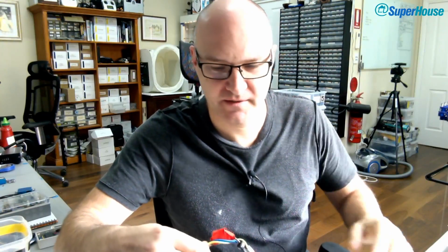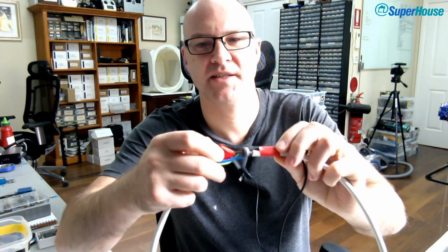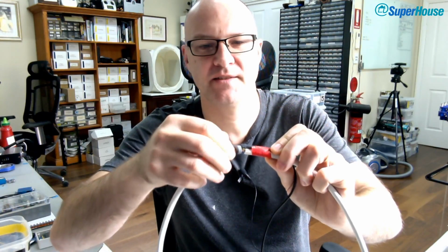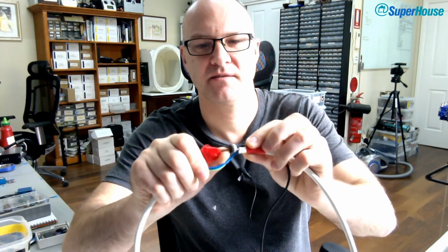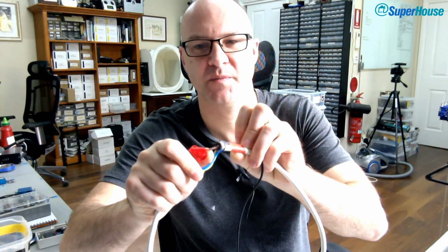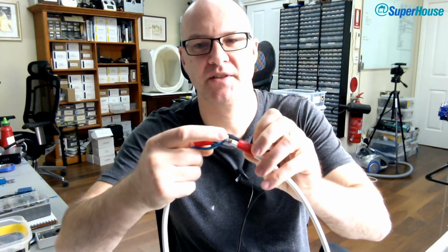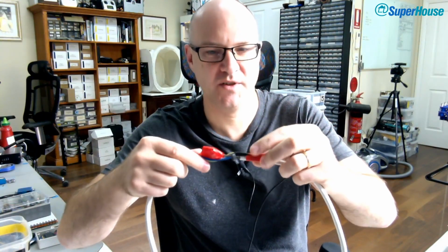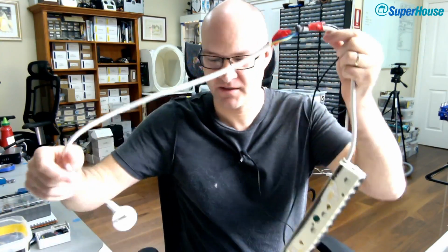And it's been cut. You can see that the active lead here has been cut and there's a joiner in there. And then the CT has been passed over the lead, so it's only over the active and it's not over the neutral. If it goes over the whole thing, it doesn't work. You have to have it just over the active or over the neutral. But active is really the sensible thing to do.